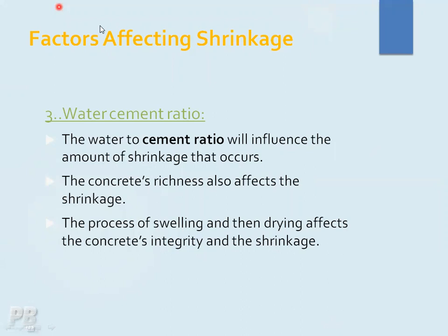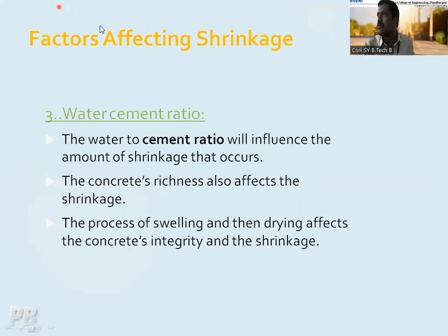No, for curing, you can use any of the materials. It may be water, or it may be some curing compounds which are available in the market, or you can use water also. No problem. Curing compounds are also there in the market right now. But again, the cost of construction goes up if you are using curing compounds.